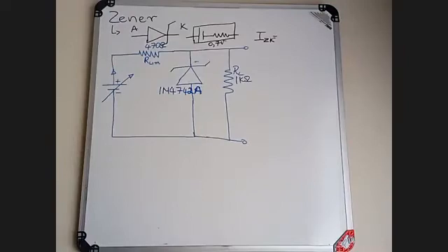You have the minimum Zener voltage, the maximum Zener voltage, and the typical Zener voltage. The parameter you must look at is the typical Zener voltage.